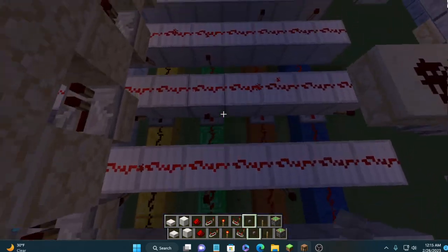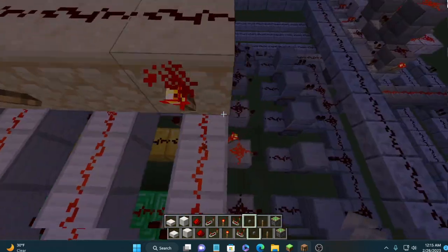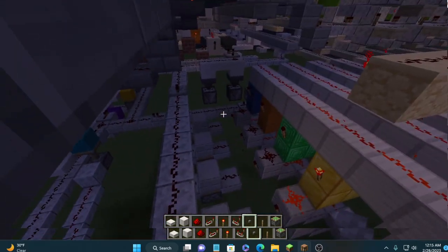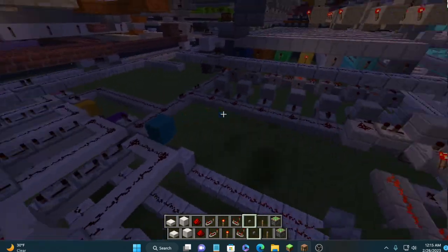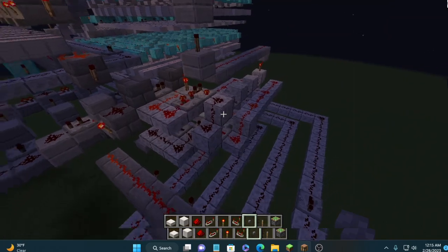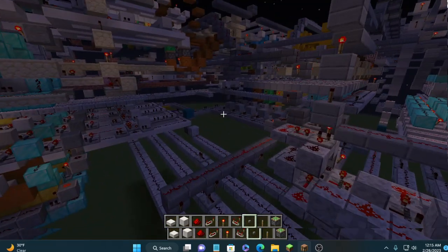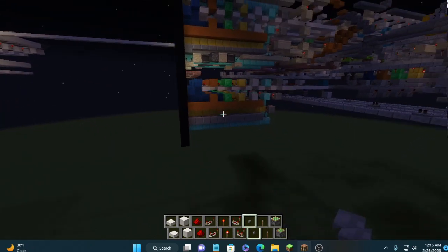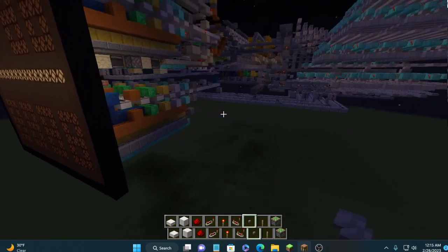I don't know if this looks familiar, but this is the same thing I have on top. It's a digit writer. This one writes the digits for the answer. It converts the 4-bit back into 7-bit for our 7-bit serial displays. The same shift register that unlocks the different lines in the double dabble also simultaneously unlocks the bottom answer displays, and that's how we shift our answer in there.